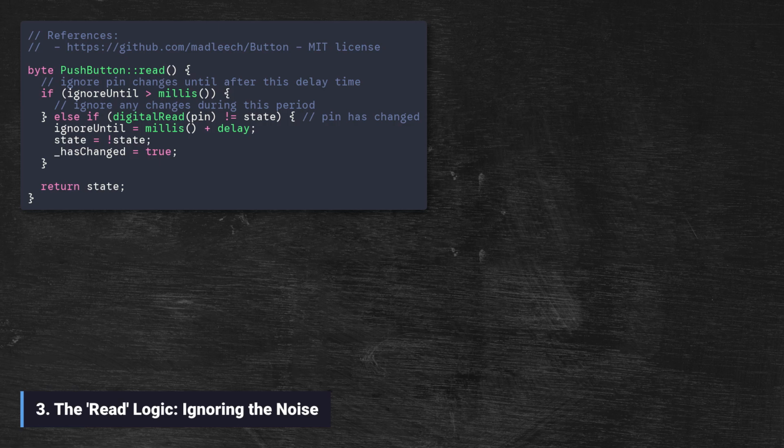Note, the condition statement, maybe ignoreUntil > millis(), will work incorrectly, because millis will come back to 0 in the future.